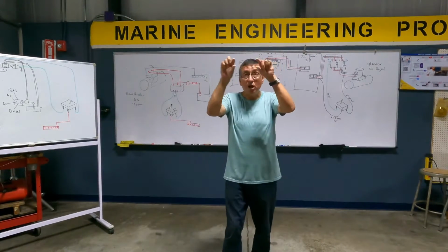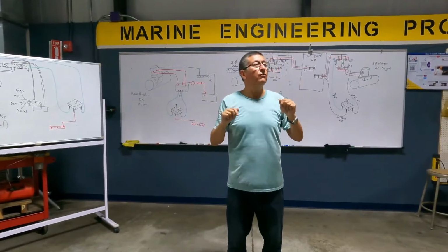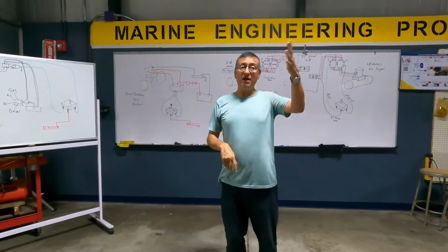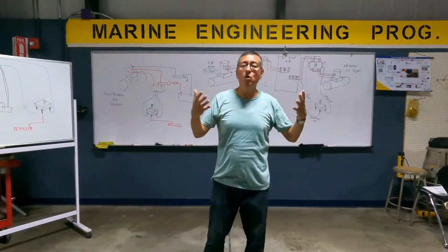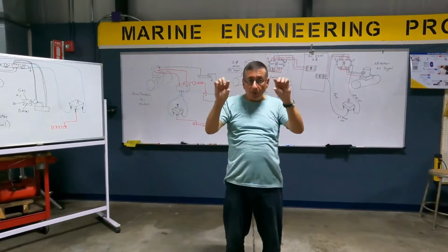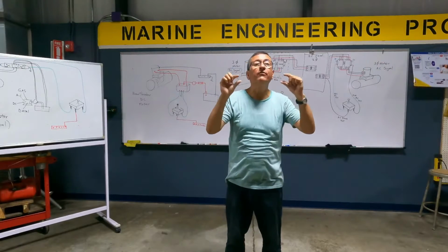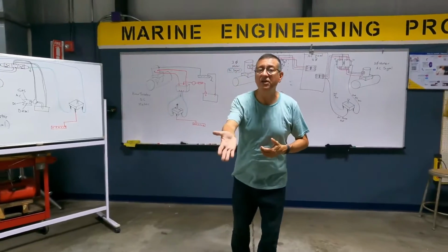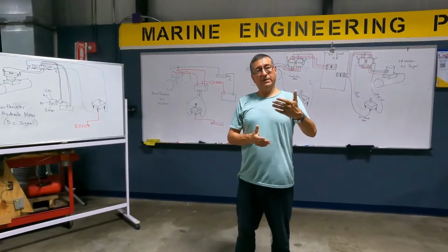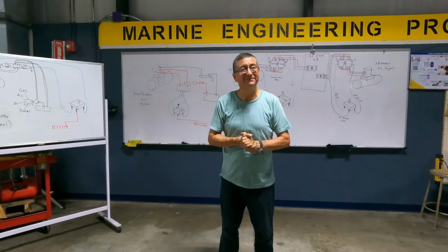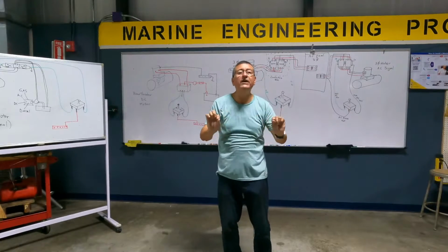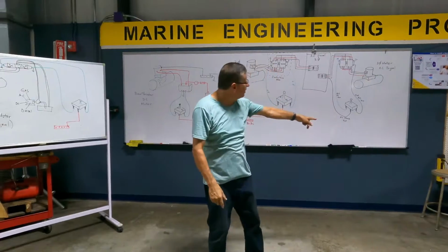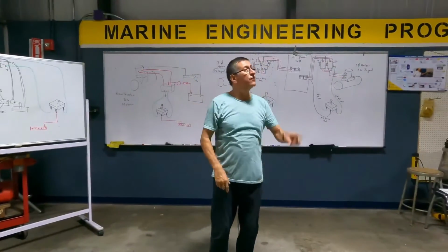I am going to use the top breakers, 3-phase breakers, for those motors: the motor of the elevators, the motor of the windlass, 3-phase motors. The second group of breakers in the bottom, double phase, for dishwashers, water heater, water maker. The single phase breakers in the bottom of that big panel are for outlets, for lights, for fans.